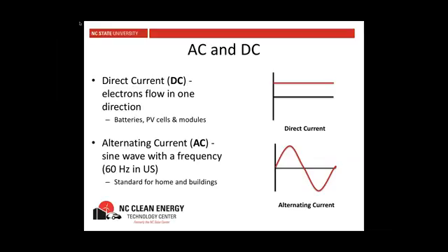On some level, it hardly makes a difference, except that because PV modules make direct current electricity, we're going to have to convert that, and we'll talk about inverters on Thursday. We can't hook up a PV module directly to a utility grid supplied house without some power conversion equipment in between the two, because we have to convert DC into AC to be able to provide power to the loads in our house or to send power back out to the utility grid.